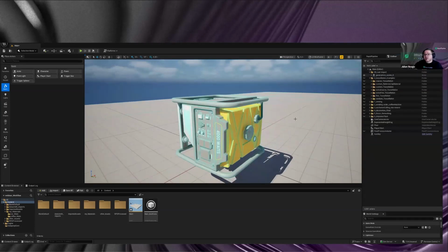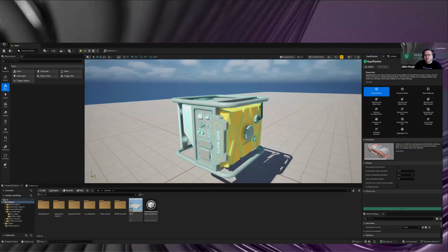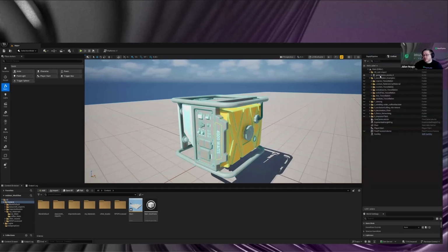What you basically get when you use our plugin, which is the interface, and perform an import of an asset, is one version populated already into your scene and into the outliner as well. In this case, it lives under the folder I created, but it would otherwise just show up in your outliner and your scene graph. It always has a root node, a root actor, and then either meshes directly under it, like in this case, or, if it has an intricate hierarchy, scene graph and parent nodes on the CAD side, or even in the FBX or whatever format you're importing, we can preserve that and the naming and everything and display the scene graph right here.